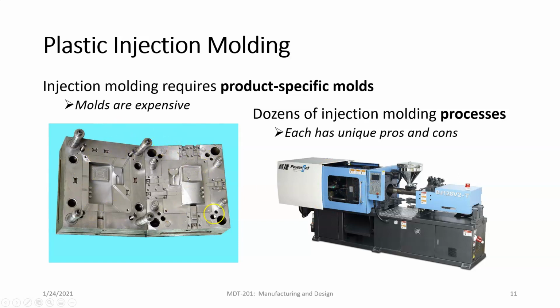Okay, so these molds or dies are very expensive because we need to machine these. We need to make these out of hard metal, and they need to have a high accuracy, right? If we don't have a high accuracy on these, then we're not going to get highly accurate parts. And high accuracy on these parts means a lot of money, right? These are very expensive and they don't last so long, so they do need to be replaced. They do need to be finished up every once in a while and taken care of. You might have some degradation in the surface that needs to be addressed.